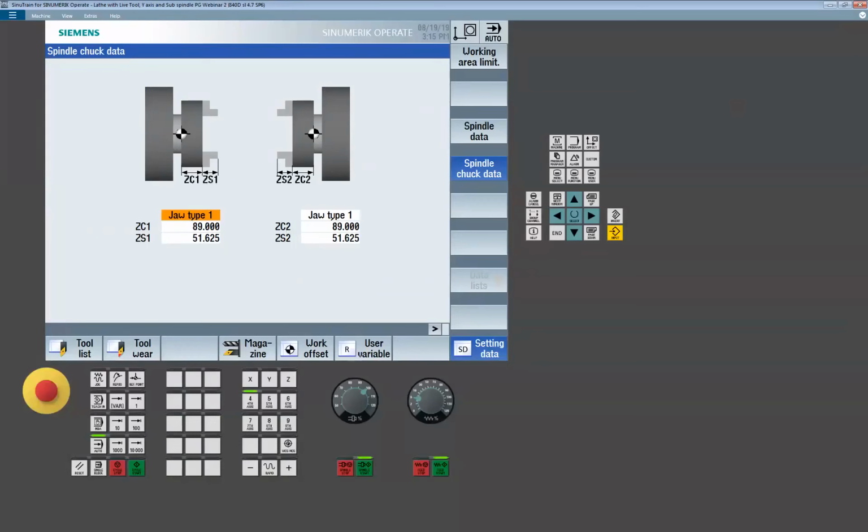Okay, so Alex is asking a question. If you add in the offset using the coupling on command, will the work offset on the sub spindle after transfer account for this offset? I.e., would the cross cut of the C0? So I believe that offset is only applied during the actual running of the two spindles. It's not shifting the 0.